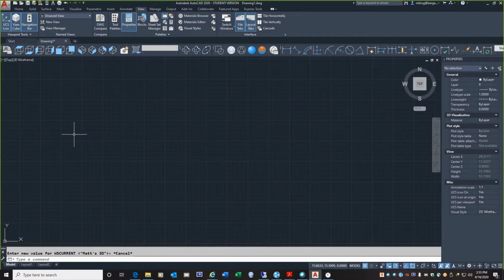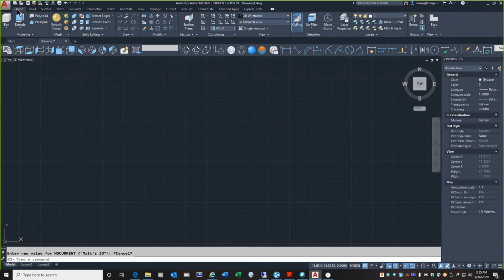So what I want you to do in the ribbon is select Home to get back to the original configuration, and all the way to the left where it says Modeling, this list on your left, you see where it says Box, click that. This is the list of those primitives. And in this list, what I want you to do is select Box, and bring your mouse into the center of the screen, and keep an eye on the command prompt.